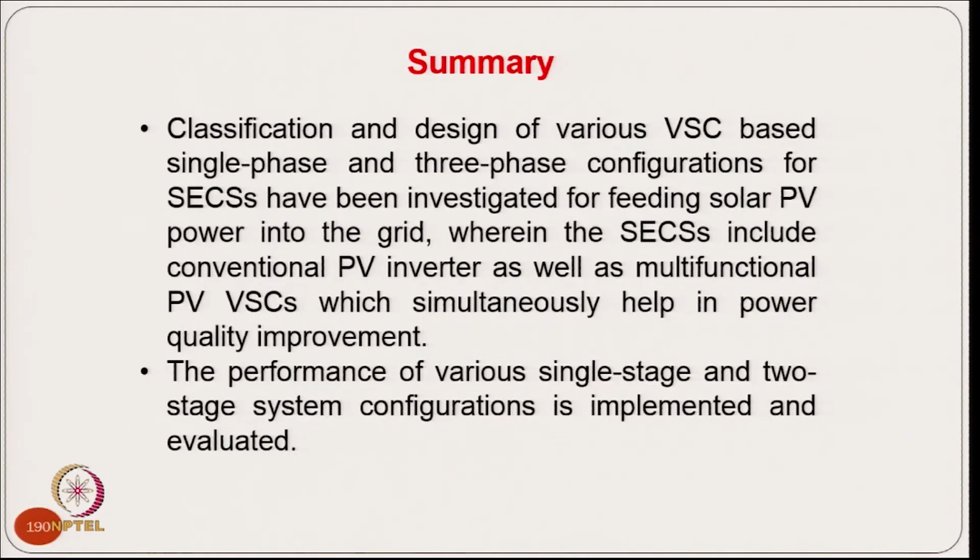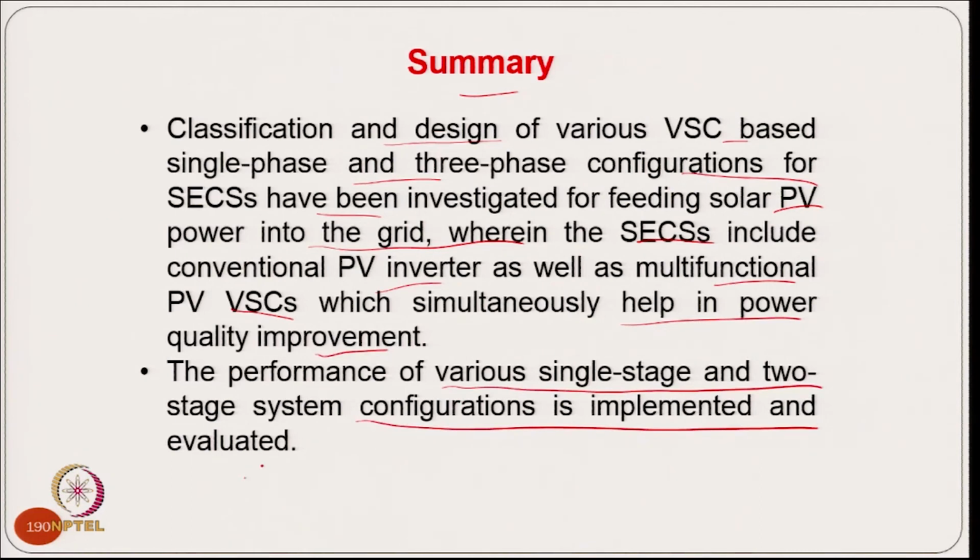So, with this we would like to now summarize the solar grid interface system. As a case study, the classification and design of various voltage source converter single phase and 3-phase configurations for solar energy conversion systems have been investigated for feeding the solar PV power into the grid, where the solar energy conversion systems include the conventional PV inverter as well as the multifunctional PV voltage source converter, which simultaneously helps in power quality improvement, and the performance of various single stage and 2-stage configurations are evaluated.